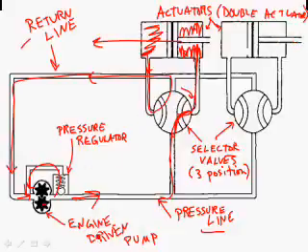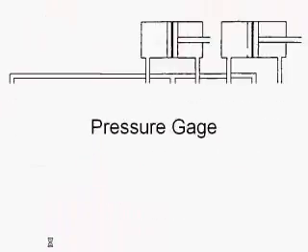power. And so we're going to have an engine-driven pump that's running all the time the engine is running, and we're going to have hydraulic pressure and be able to displace a volume in this pressure line whenever we need to. This is the kind of system you're going to see, transport category jet, big biz jet, big turboprop.